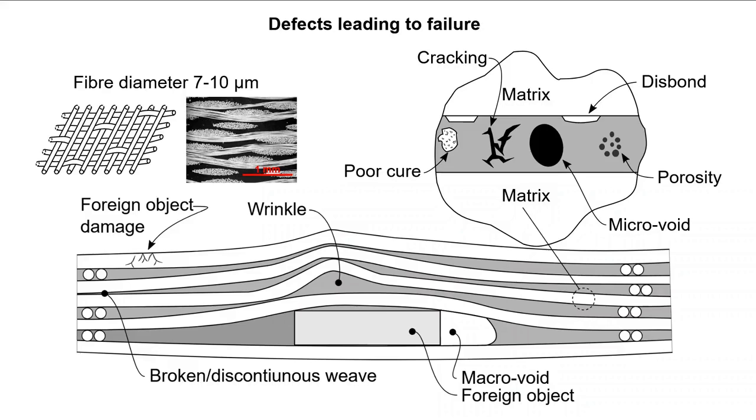While the mechanisms might be slightly different, there are definitely parallels with the types of defects that can occur in metallic systems. What's important to note is that the initiating defects in composite systems can appear in the reinforcement first or the matrix first, but the end result will be propagation of some type, with the two preceding examples of interfacial failure and fiber pullout being examples.